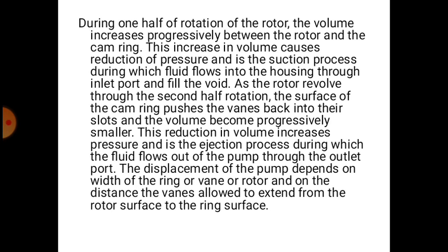As the rotor revolves through the second half rotation, the surface of the cam ring pushes the vanes back into their slots and the volume becomes progressively smaller. This reduction in volume increases pressure and is the ejection process, during which the fluid flows out of the pump through the outlet port. The displacement of the pump depends on the width of the ring, vanes or rotor, and on the distance the vanes are allowed to extend from the rotor surface to the ring surface.